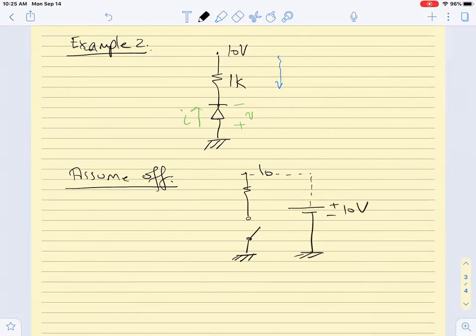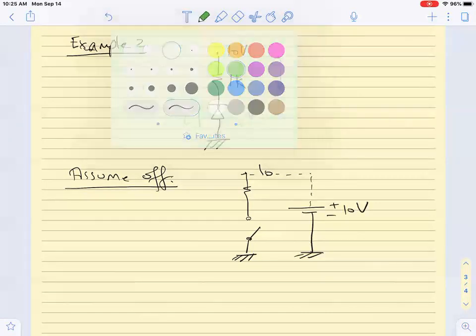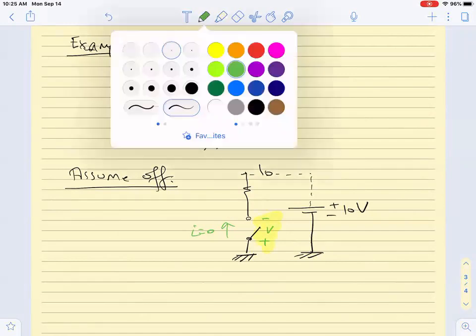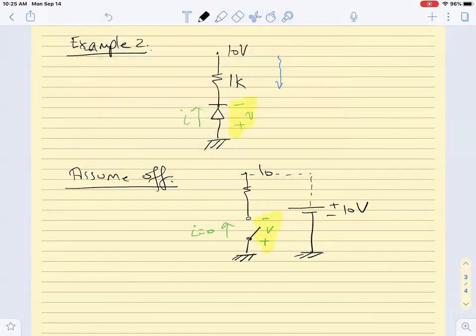Okay, so the current of the diode is still going up, but now I is really equal to 0. And where is the voltage across the diode? As it was drawn at first, we don't change it. Okay, so this is very important when you verify that we keep the same voltage direction for the diode. And now if I want to apply KVL, what will I say? This is connected here, right? If I apply KVL, what do I say?